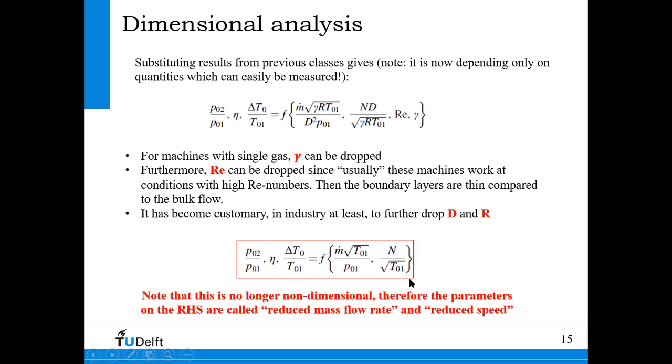If you really look at the high efficiency equipment used in industry, this all plays in a kind of inlet Mach number and rotational Mach number. They normally call it the reduced mass flow rate and reduced speed. These 2 parameters are normally used to make your inlet parameters non-dimensional and to be able to scale to each other. That way you can apply it to all the temperatures, and for instance also to all the fluids, and it would be easy to do it like that.